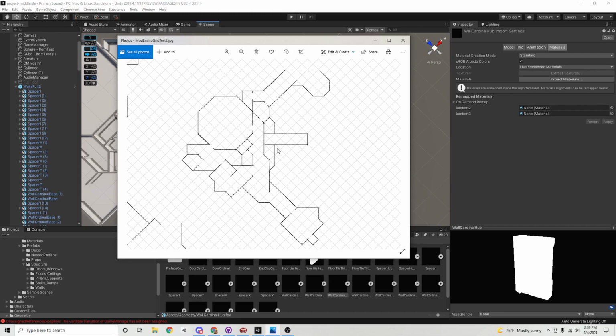It's really important that you sketch it out on a grid like this, otherwise you're going to get imprecise, and then suddenly none of your walls are actually going to line up with each other, because the walls line up in a very precise way. And if you're not exact constructing the environment the whole way through, you're going to get pieces that are a little bit off, don't quite connect, have a tiny little gap that none of the pieces fill. You get that problem in other ways too, mainly by not following the rules I'm about to outline and demonstrate for you, but that's the main one. So no matter what, you need to sketch out your environment on this grid like this.